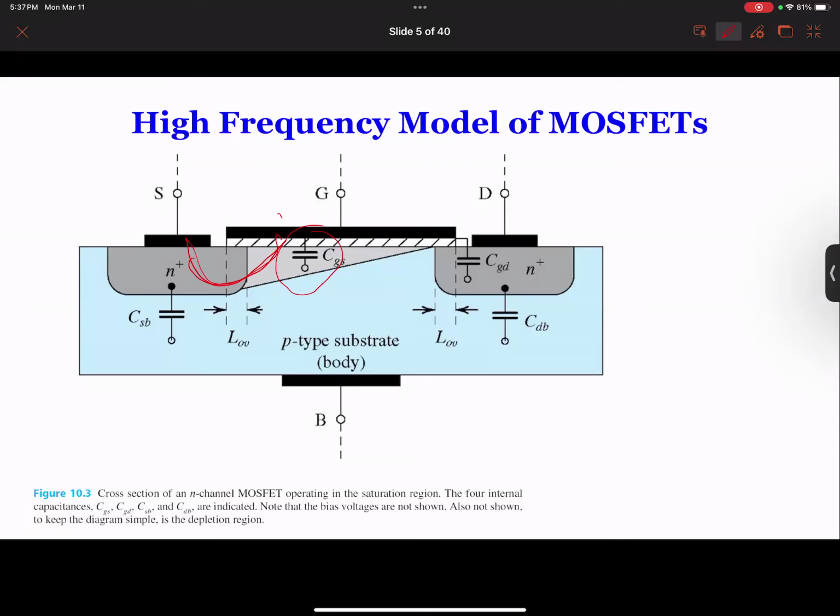Of course, you might say, oh, you have to have two parallel plates. No, you don't have to. Even two plates like this will have capacitance. It's just that the capacitance is smaller than if you have this. Two plates like this have very big capacitance. If you shift it like this, it's smaller, right? Because the overlap is small.